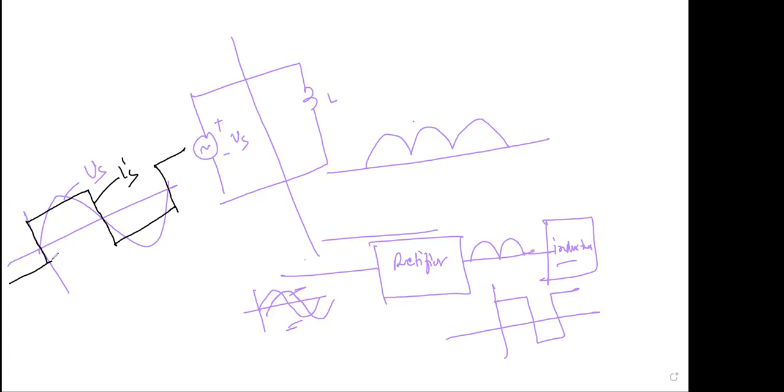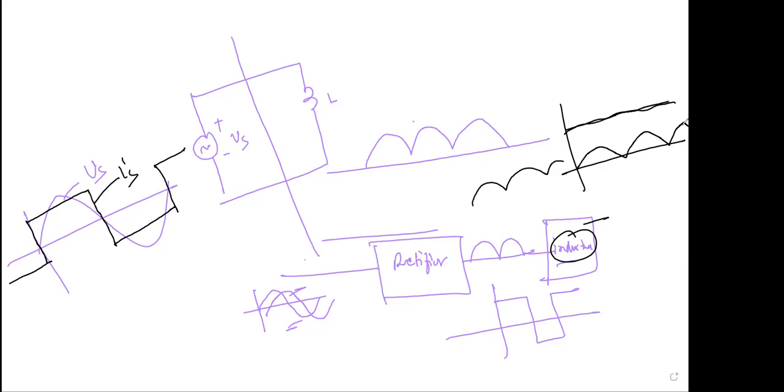Sir, 0. Here, I told you that your inductance will be very high. So your input voltage is like this. But since a highly inductive load is there, or high inductance you have inserted, the current will not discharge, rather the current will be just DC. You got my point or not? Yes, sir. This is your output voltage, but your current will be constant because you have inserted very, very high inductance. You understand it? Yes, sir.